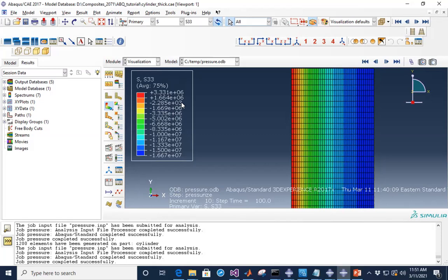So as we just discussed, the stresses here from Abaqus match really well with what we expected from an analytical solution. However, that might not always be the case. Here, we use 40 elements, and we used a quadratic type of element in our mesh. So these numbers seem to match exactly. Now, what I'm going to show you is how we can quickly change the mesh and how that's going to change these comparisons. So let's go back now under this module menu. Let's now go back to the mesh module. I want to remesh it with a slightly different mesh and show you what happens.